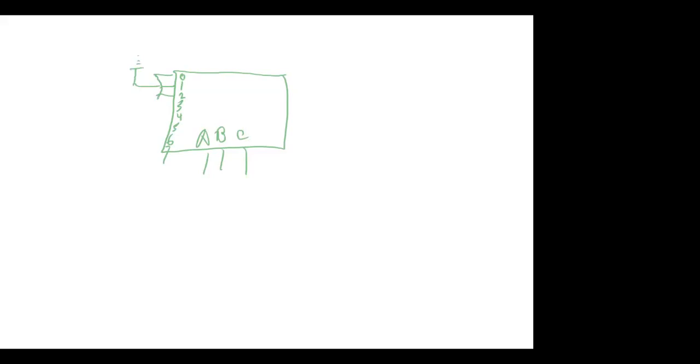And then we'll take D3 and we'll wire it to +5 volts. We'll assume that's a 1. And then we'll run D5 and 7 to the same place. And then we'll take D6 and D4 and we'll run them together.